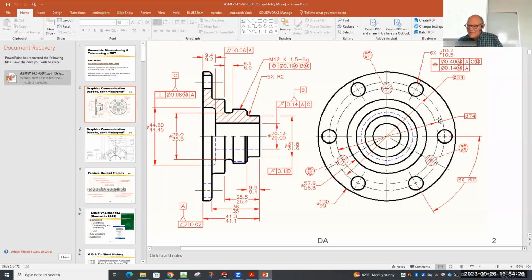Well, you've got a hole pattern here, and there's a bolt hole circle right here. If you follow it along and find what the diameter is of that circle, it's right here, and it's 84. It's not 84.2 to 85.5. It's a box around the number 84. That is a basic dimension. If you put a tolerance there, now I'm going as a machinist, wait a minute, I've got a positional tolerance and I've got a starting point tolerance, and now you get stuff that's impossible to do.